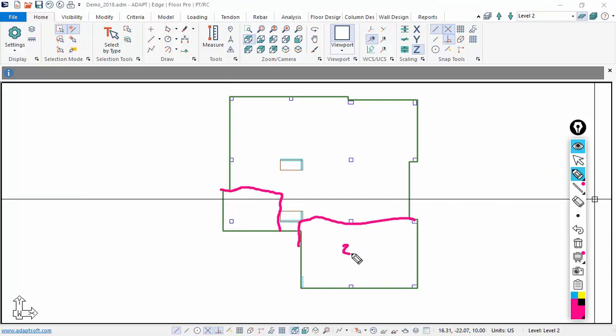So this is going to be 8.5 inches. And then we're going to have basically a step here and here. This will be a step. This will still be 7 inches, but we're going to drop it down by one inch. So how do we do this? We can either use adjoining slabs, or we can nest slabs. And there are pitfalls, I think, to either method. For a single level slab like this, I'm just going to nest the slabs on top of one another.